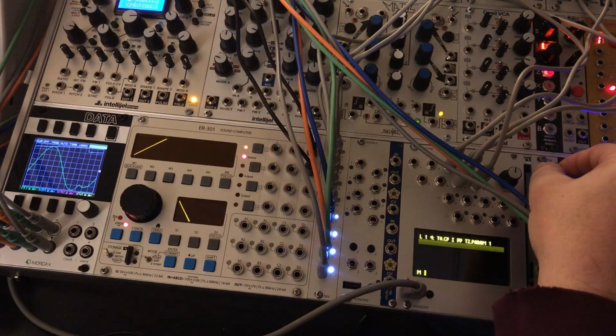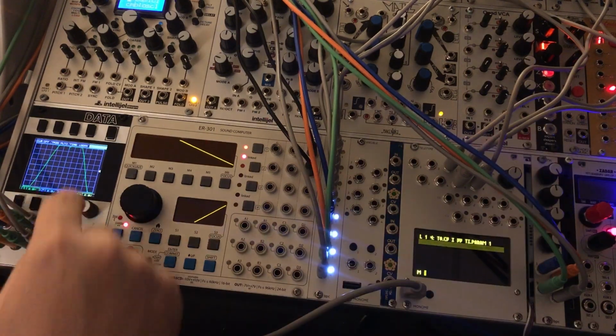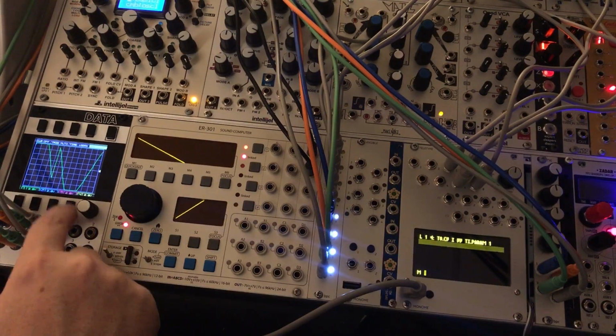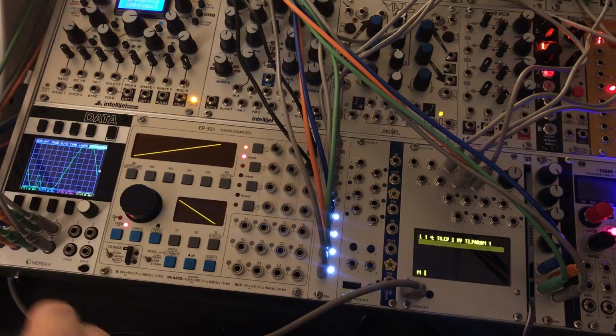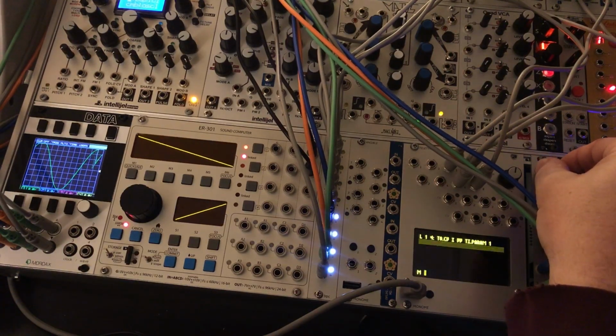And as I start to bring it up, I've got the voltages here set to 2 volts. We've only got a display of 4 here, so it's cutting it off a little bit on the scope. But it's going 10 volts peak to peak here. Cool.